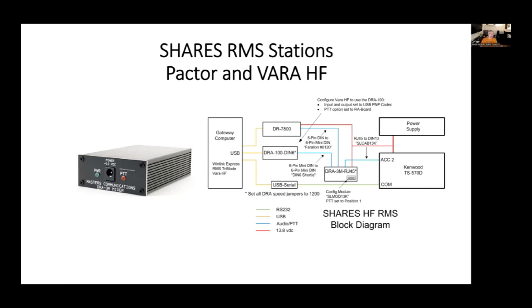So what the mixer basically does is takes the 2 sources, creates one, and that's connected to the radio. The mixer is not passive, it's active. And that's why it's got a 12-volt power connection out the front. In this case, the mixer requires 12 volts DC. That power has got to be clean. We have had some instances where people have had trouble.